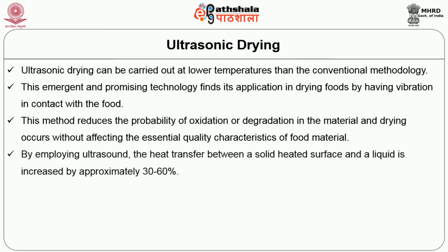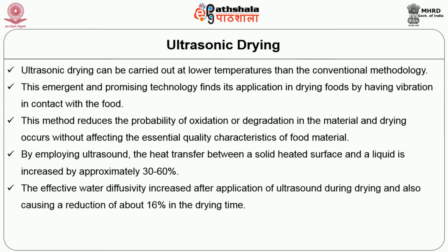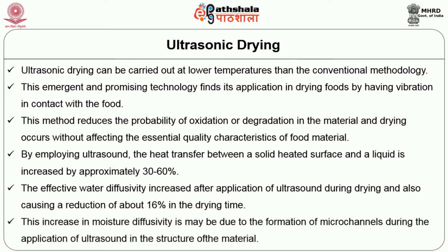characteristics of food products. By employing ultrasound, the heat transfer between a solid heated surface and liquid is increased by approximately 30 to 60%. Also, the effective water diffusivity increased after application of ultrasound during drying and also causes a reduction of about 60% in the drying time. This increase in moisture diffusivity may be due to the formation of micro channels in the structure of the food material during the application of ultrasound.